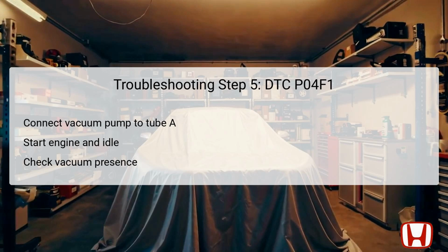A before starting the engine. After ensuring all connections are secure, start the engine and allow it to idle. During this phase, it's crucial to observe whether a vacuum is present in purge tube A.